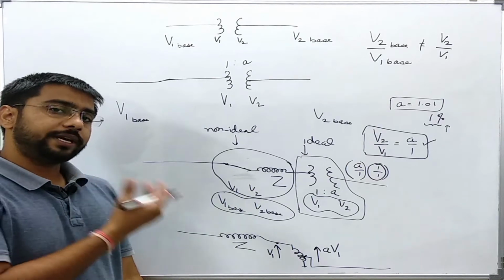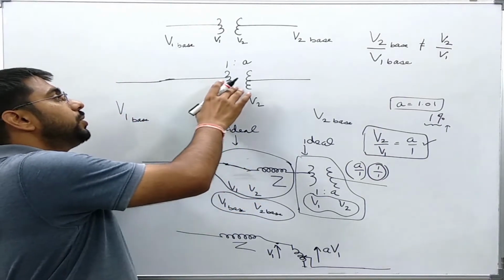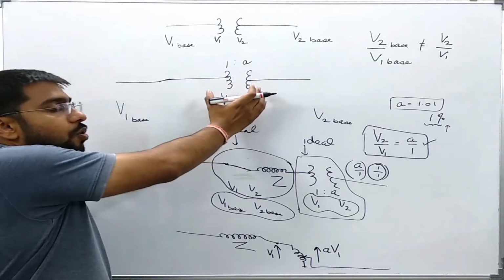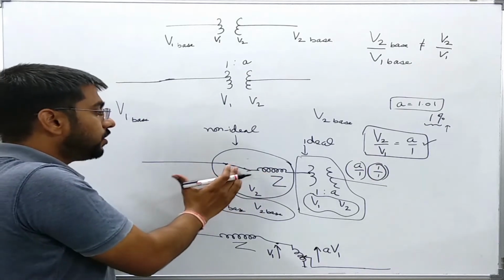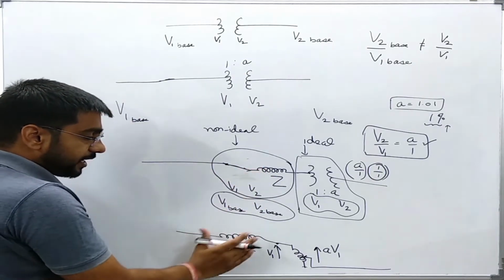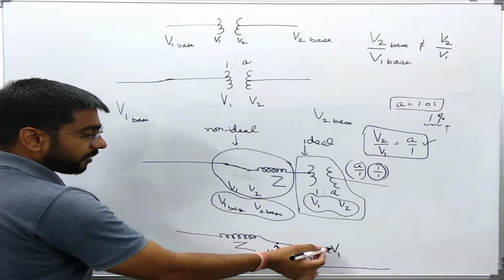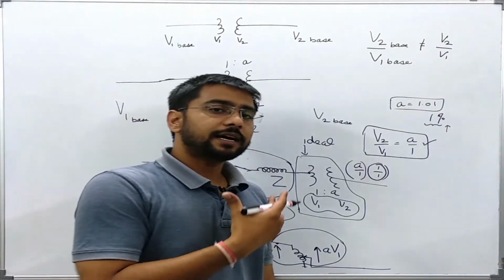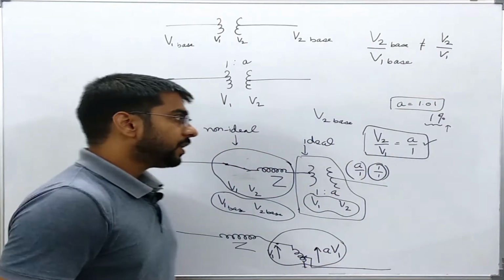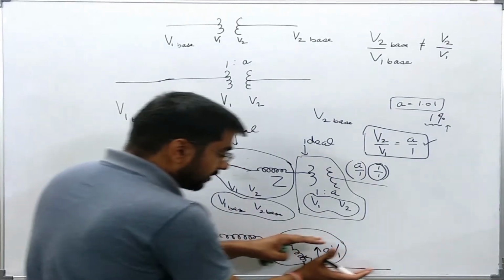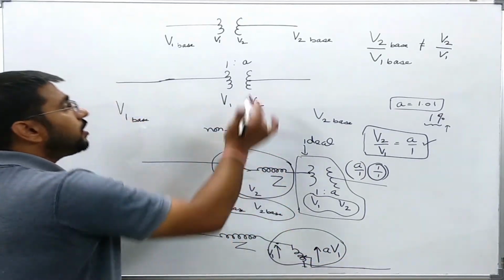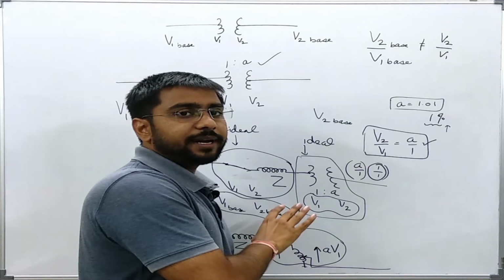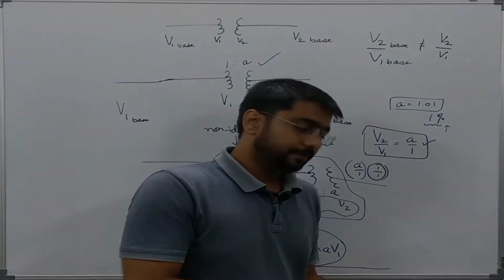So what I have tried to do here is to show this off-nominal tap ratio transformer by giving all its non-idealities to a transformer which can be easily shown just by an impedance in per unit form, and the other transformer is ideal and just changes the voltage and current levels, with no other non-ideality present in it. Now we have some kind of very simplified equivalent model of this transformer. Now we will try to determine its Y admittance matrix in the next slide.